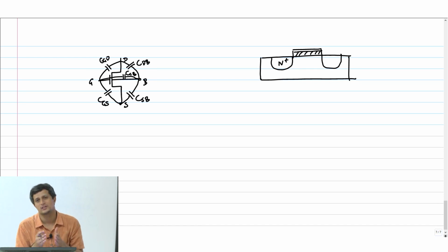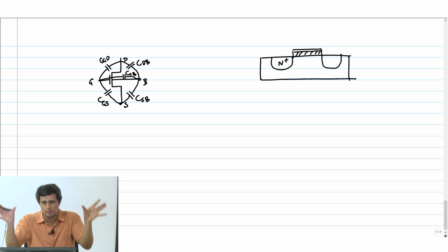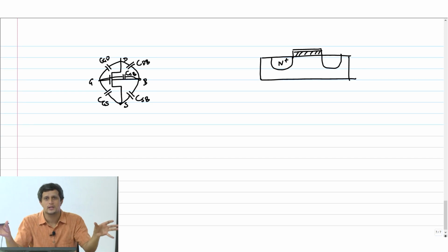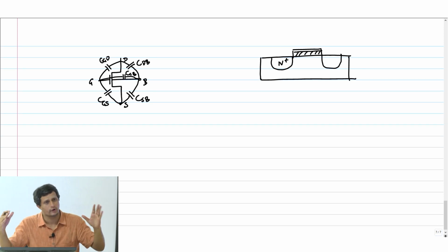This in fact is manufactured in something known as a self-aligned process. You grow the silicon, make everything silicon dioxide, then put a mask and then harden one region and make the other soft. Then you etch out the soft regions.